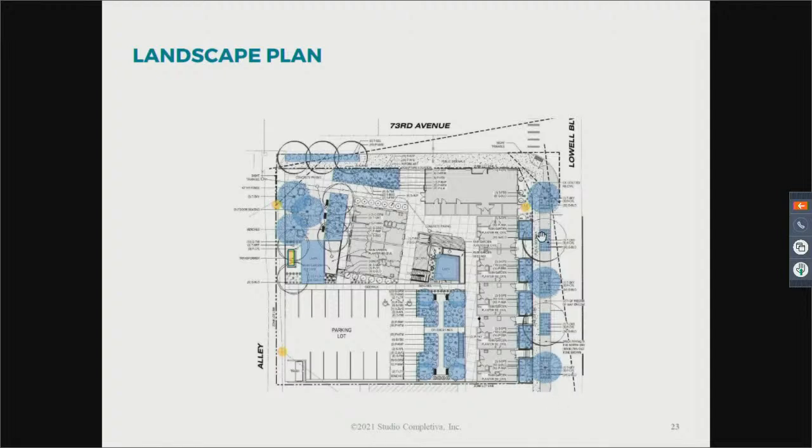The remaining water on that building feeds into the lawn in the middle of the project before traveling towards 73rd to an inlet on the northwest corner of the property. And all the precipitation falling on the 2-bedroom units, which are that smaller building that's rotated, will feed into a rain garden and planting area before feeding into that same water inlet on the northwest corner.